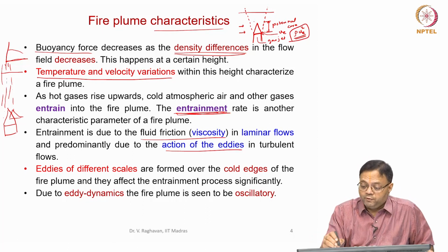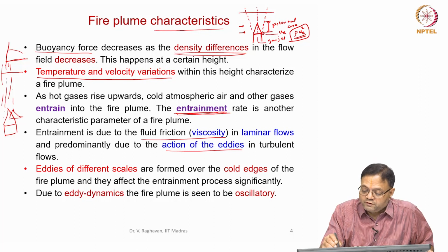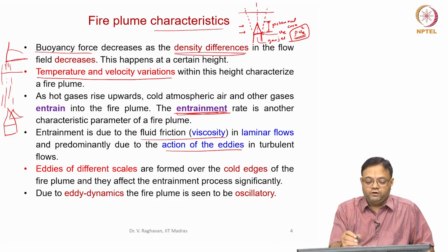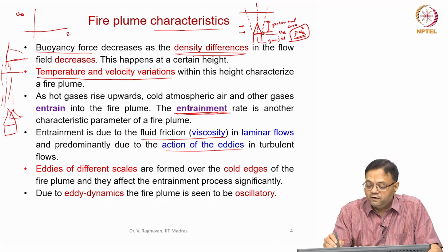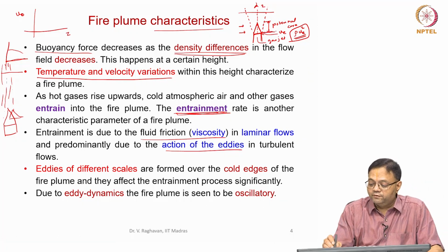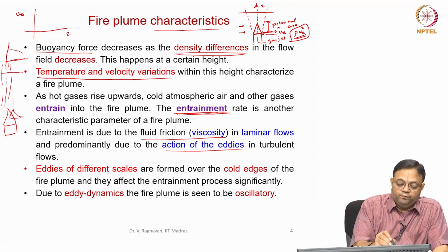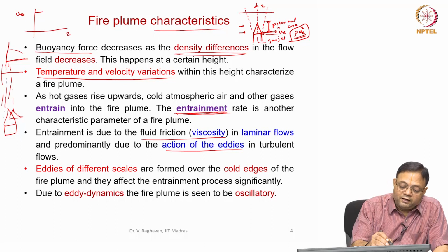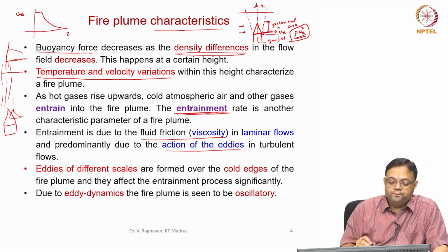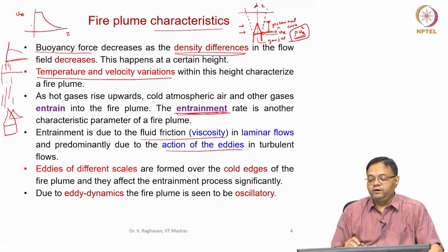Okay. Now, what happens to the velocity? If you take the central line of the jet, the velocity of the central line basically can be plotted. So, I will say Uo, center line velocity versus height. Height is Z here and this is radius R. So, this remains constant in the potential core region and then decreases. This is called velocity decay.